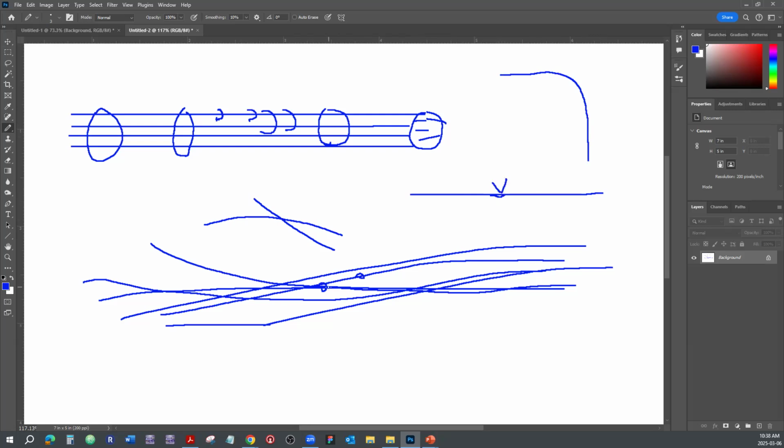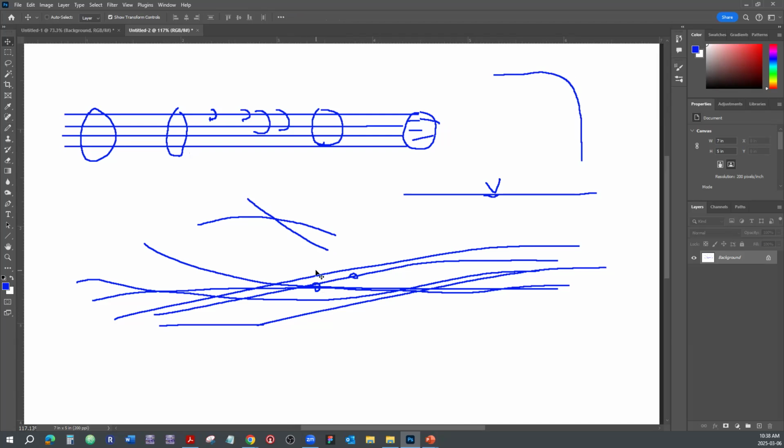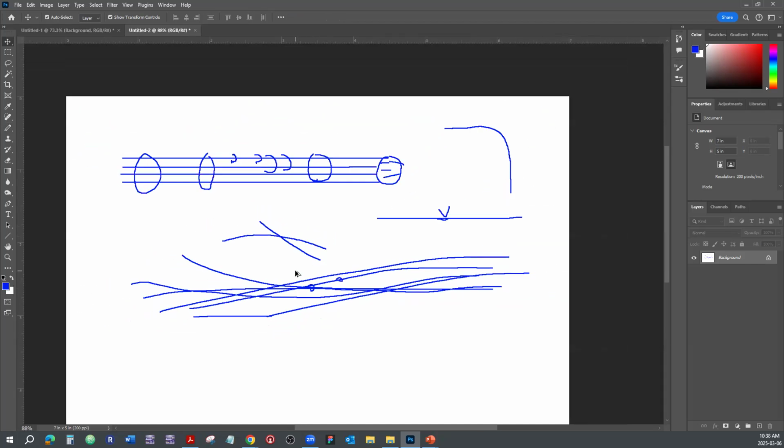So you could create a bunch of micro bends which are going to change the specifications of the cable. It's just like tying it with zip ties and squeezing them hard, or stepping on those wires when they're on the floor while they're being pulled. So I gave you the two situations, and I gave you the reasoning.